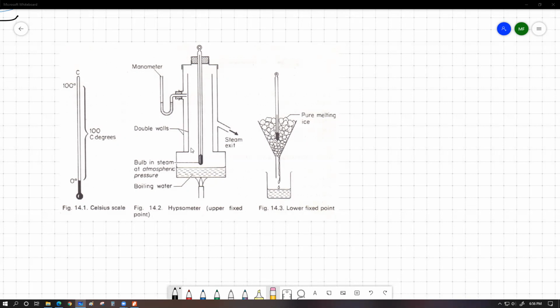So that's why we have this whole second layer cover. Because we are continuously providing heat, there is continuously boiling water, so steam is continuously being produced. If we do not allow this steam to escape at all, this is going to work like a pressure cooker, where boiling is happening, but the gases are not coming out. In that case, inside pressure would become higher than the atmospheric pressure. So this level should become low and this level should become higher, representing that inside all of this contraption, the pressure is higher than atmospheric pressure.